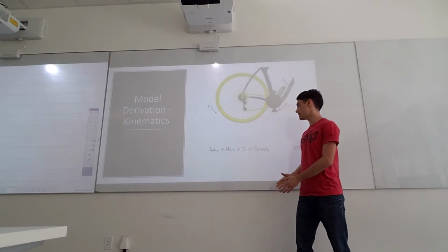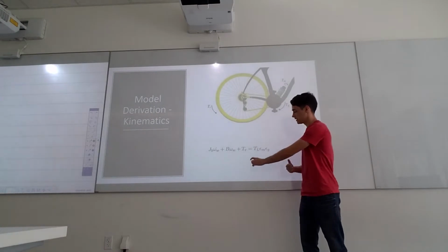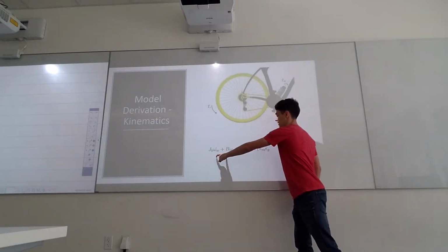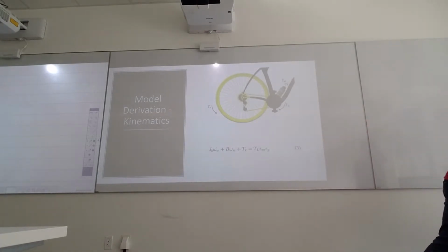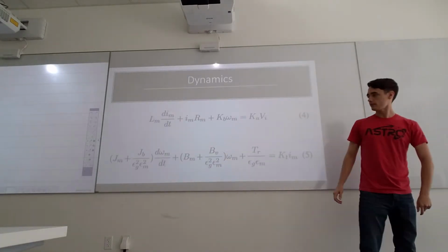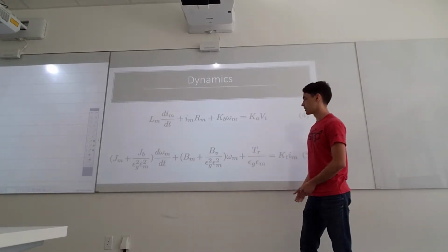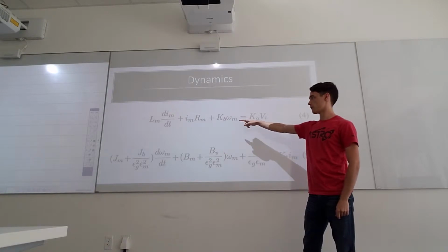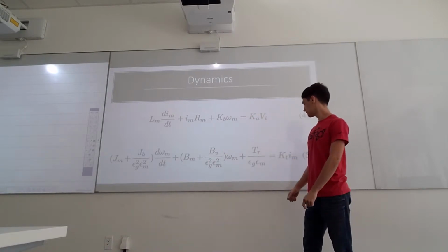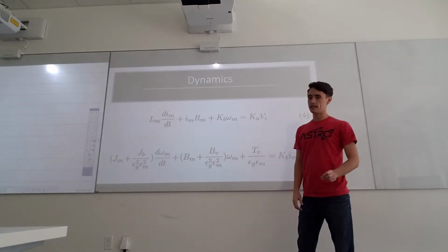So we're going to combine these models together by using this TL term. So all you have to do, divide everything by the gear reduction ratios, you get TL by itself, and then we're going to go back to our motor equations, and by plugging them into the second inertial equation of the motor, we find these. And this is just the first equation of the motor rewritten when we originally did the KVL. So same things, we've just organized it in terms of states now.